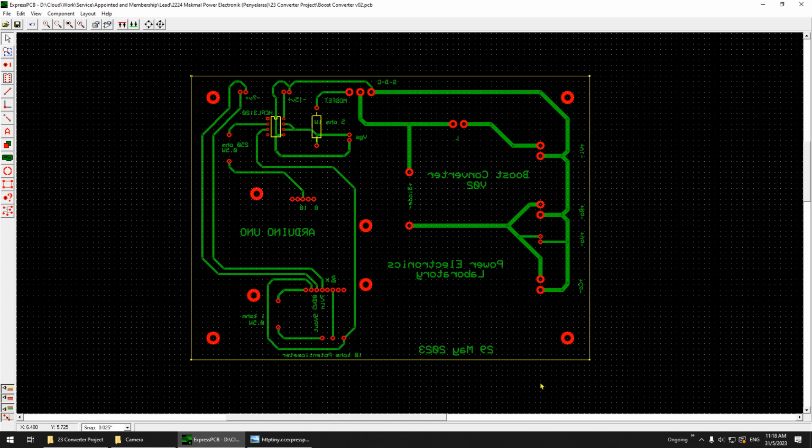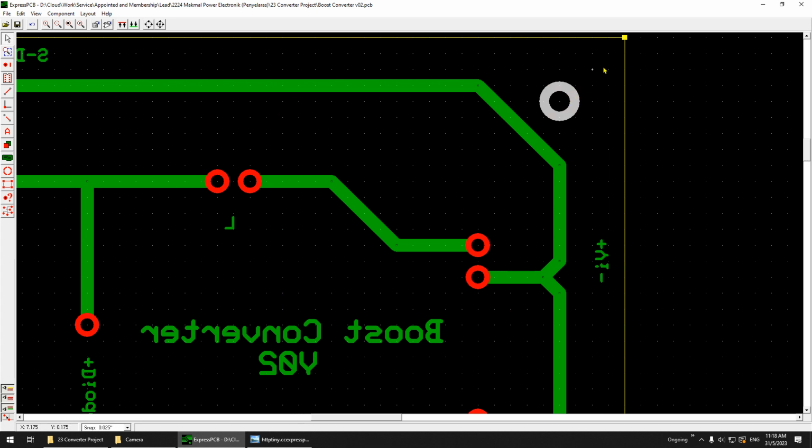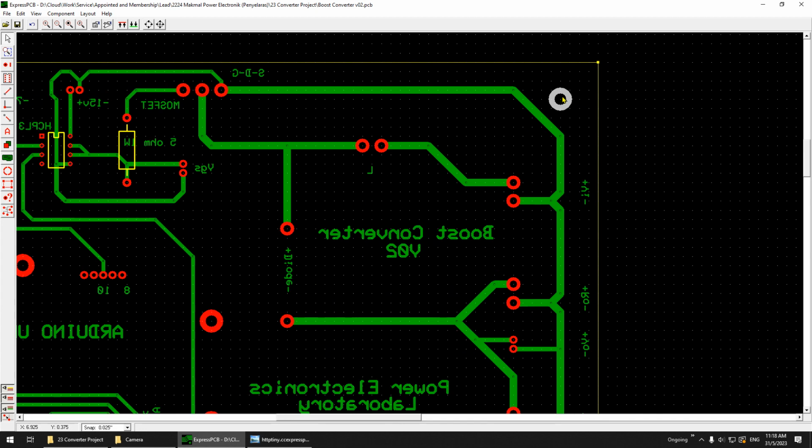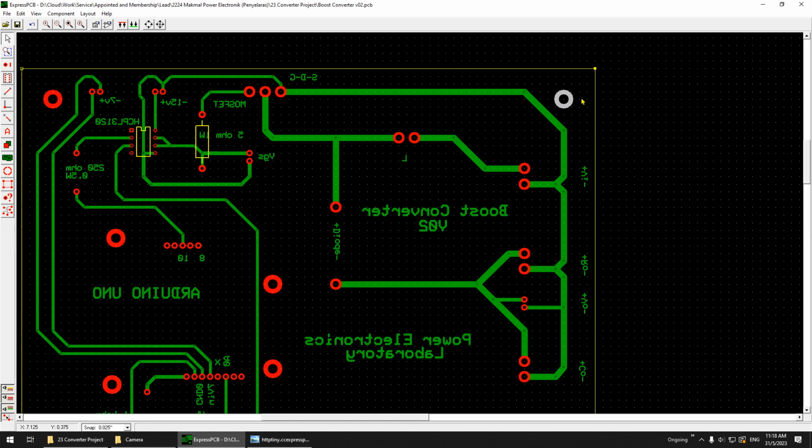So that is the first thing, and then the second thing, you have to put a PCB stand. You can see here, this is the PCB stand. I suggest you put a minimum of 4 at each side, and make sure you don't put them too close to the edge. You cannot put it like this, because usually it will break. You need to put it a little bit deeper in, you cannot put it at the end. Last time I did this, it broke. So I suggest putting it a little bit inside.